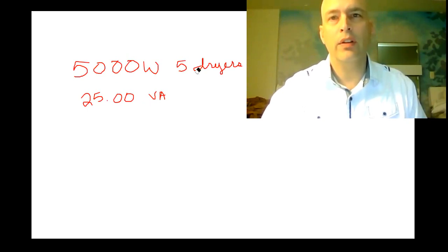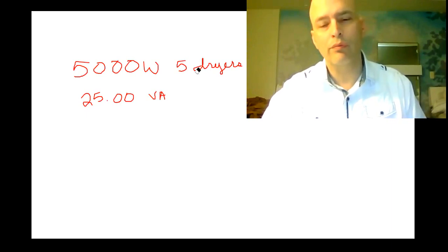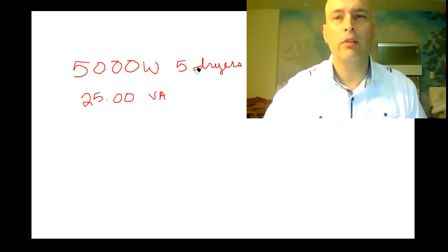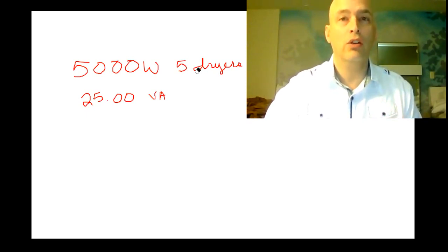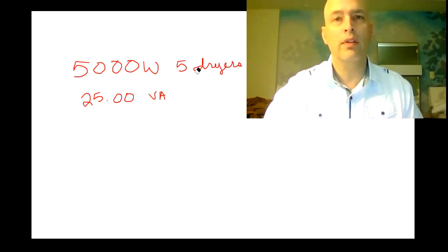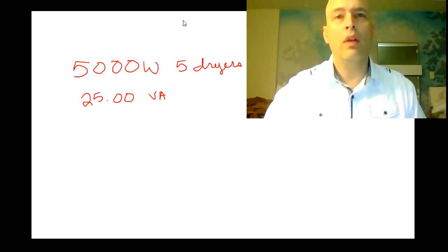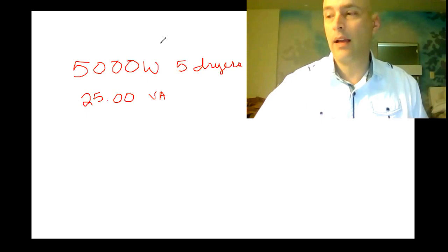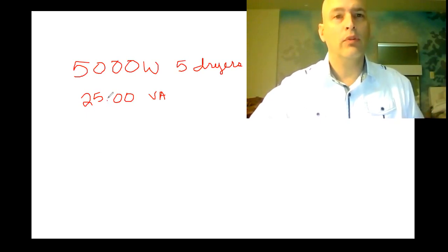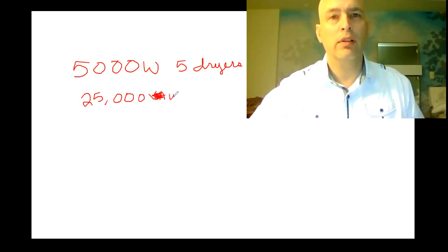Now it is interesting to know that on this test, or when it comes to calculating specifically electric dryers in a residential setting or electric cooking units, ranges, ovens, things of that nature, the code actually does specifically tell us that a watt and a volt amp is the same thing. So we can use those interchangeably in this kind of appliance setting. So 25,000. Again, I said I was going to use watts, so let's just use watts there to stay with convention.